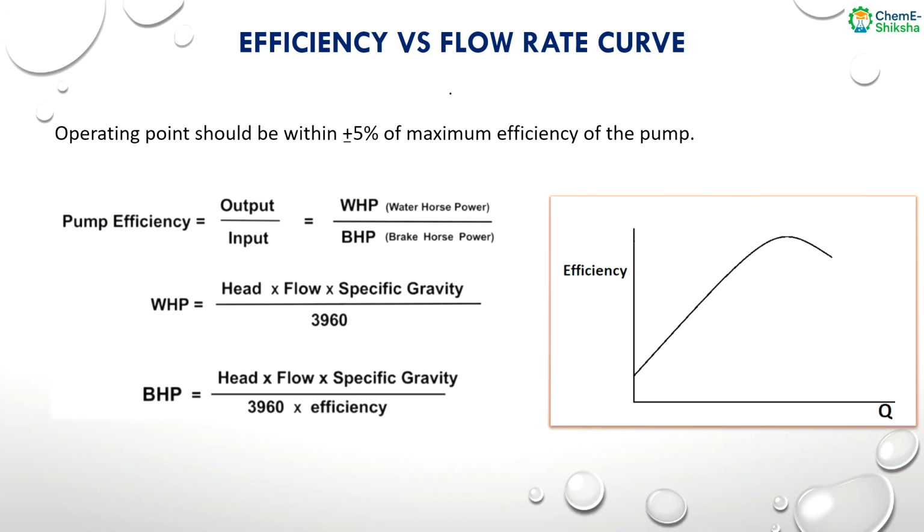Now this is the efficiency versus flow rate curve. Before that, let us talk about the pump efficiency. Remember this, efficiency means output by input. So for a pump also, pump efficiency equals output by input. Here it is WHP, the water horsepower, divided by the brake horsepower.